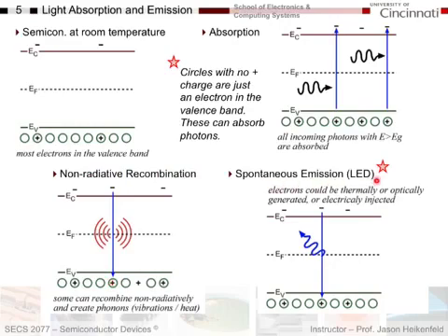As we've learned previously, if we have a light-emitting diode, we can get spontaneous emission. That's an important term, which is going to start to differentiate when we talk about LEDs and lasers. Spontaneous emission means that I have electrons and holes. They can at some point randomly or spontaneously line up, recombine, and a photon can be emitted in any direction at any time. And so it's spontaneous. It's not something that you necessarily control or predict. Electron-hole pairs line up, photons are emitted, and it can go in any random direction. Spontaneous emission, the basis for LEDs.